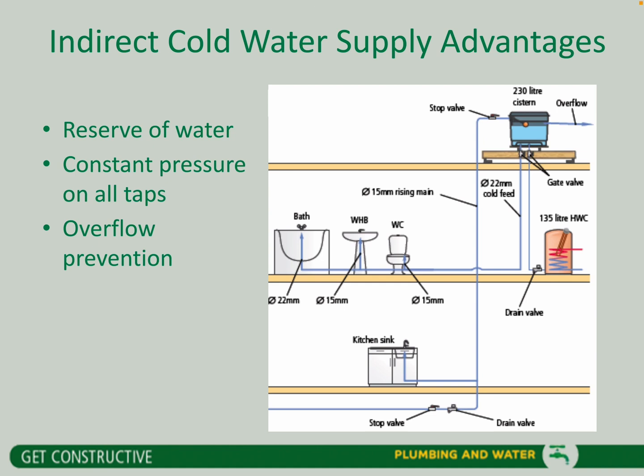They obviously have some advantages. First thing I want you to point out or notice is that we have a mains coming in and still going to our kitchen sink. From our kitchen sink, it's then going up into the attic, up to a 230 litre cistern. You'll notice this cistern is much bigger than the previous ones. The reason this is bigger is because this is then feeding into your toilet, your bathroom sink, and your bath. Okay, and obviously your shower as well. So that's then feeding into the rest of it.